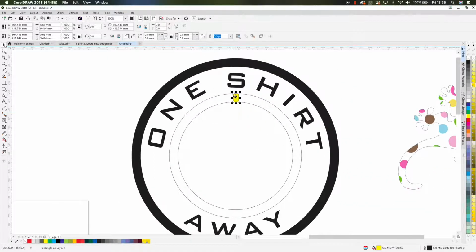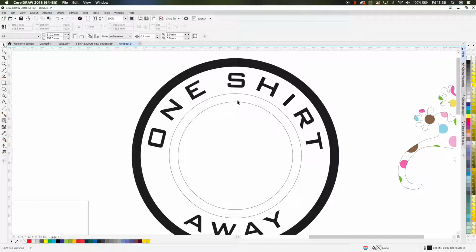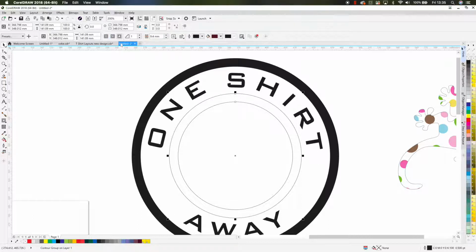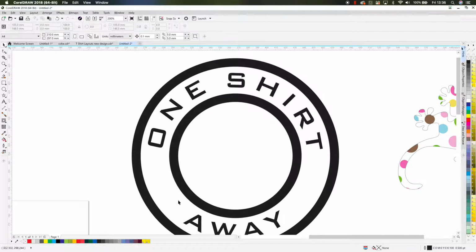And again, I want to make that two individual components. So I'm going to delete that little square out of there. And I'm then going to click on the circle, and you can see the circle just gives me the size. If I select the outer circle, we know that is the contour. I'm going to go up to the top menu, Arrange, and Break Contour Apart. I'm going to click once on the inner circle, hold down the Shift key, click the outer circle, and grab both components. Control L, that's combine, and then I can fill it with a colour of my choice, or my client's choice.